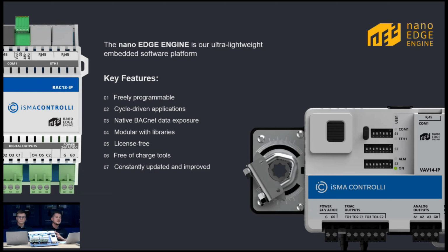So let's look at some key features of Nano engine itself that are shared throughout our controllers. First of all, it's fully programmable, and it's based on cycle-driven applications. That means you can create applications using logic blocks and a wiresheet, and you can drive not only one, but multiple applications in time cycles. Those can be different time cycles for different kinds of applications, even on the same controller.